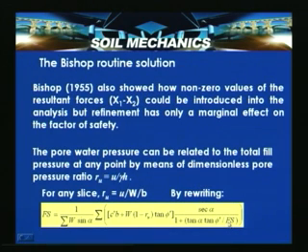Bishop 1955 also showed how non-zero values of the resultant forces X1 minus X2 could be introduced into the analysis, but the refinement has only a marginal effect on the factor of safety. The pore water pressure can be related to the total fill pressure at any point by means of a dimensionless pore pressure ratio.